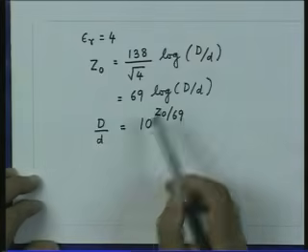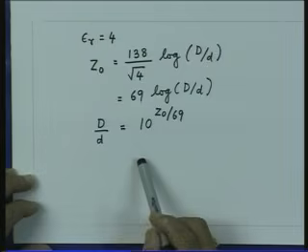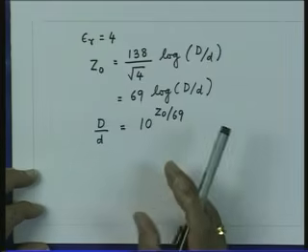What that means is that the coaxial structure is more suited for realizing low characteristic impedances. That is the reason the coaxial lines used in practice typically have characteristic impedances of 50 ohms, 75 ohms, something like that. But if I want to realize a characteristic impedance of 200 ohms or 300 ohms, it will need a structure whose size will be physically prohibitive.